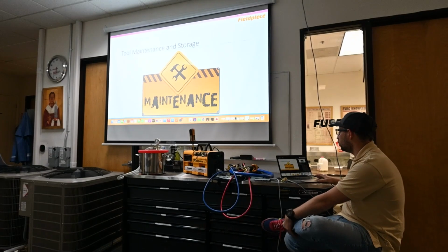If the pressure does not go to 50 microns, first change the pump oil. If the pressure does not fall to 50 microns after changing the oil, the pump and gauge are suspect. Most HVAC and refrigerant pumps will create less than 20 microns if run long enough. Tool maintenance and storage. Maintaining tools is necessary to keep them working when they are needed.